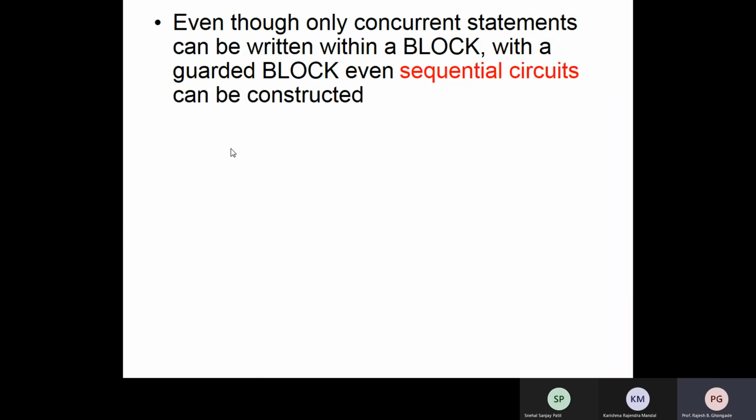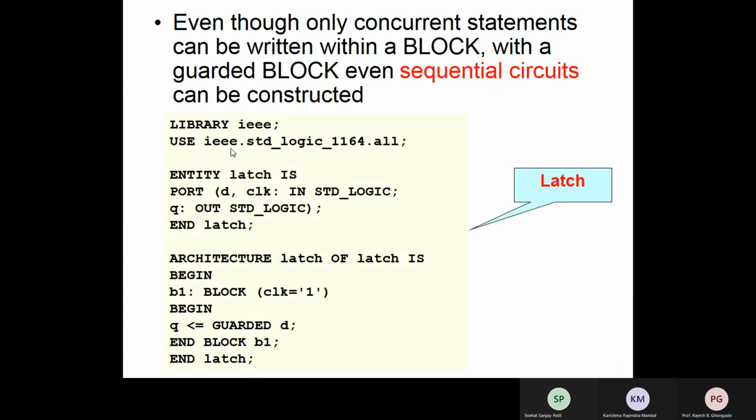Please remember that it doesn't mean that only concurrent constructs can be used to construct combinational logic and sequential statements only sequential logic. It is not like that. It is quite possible that you can generate combinational logic with sequential statements also, and vice versa.